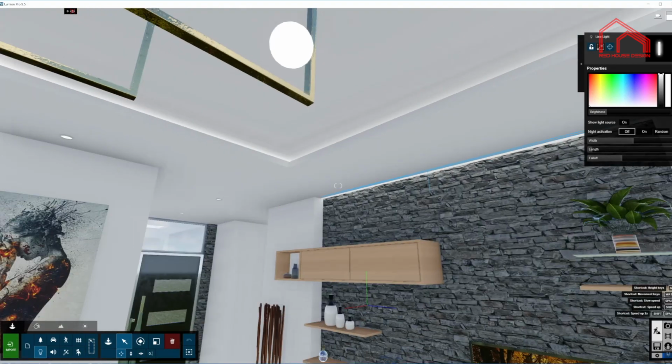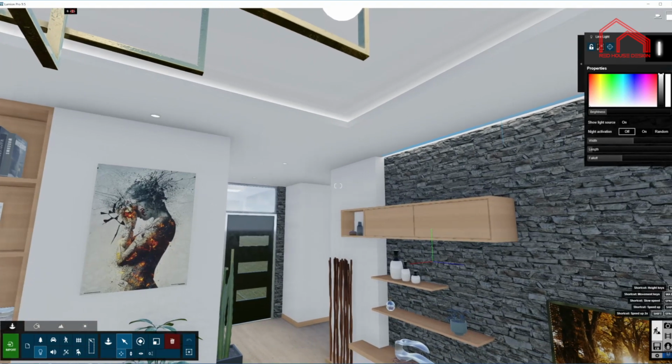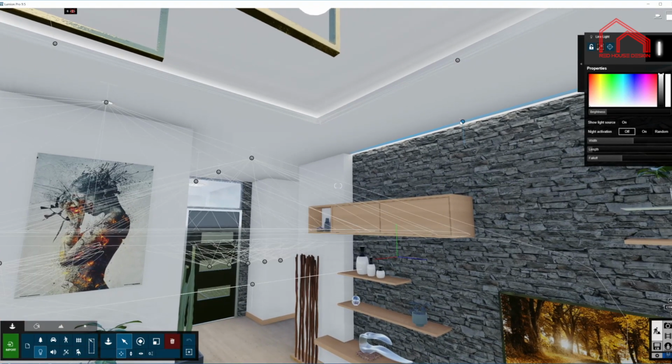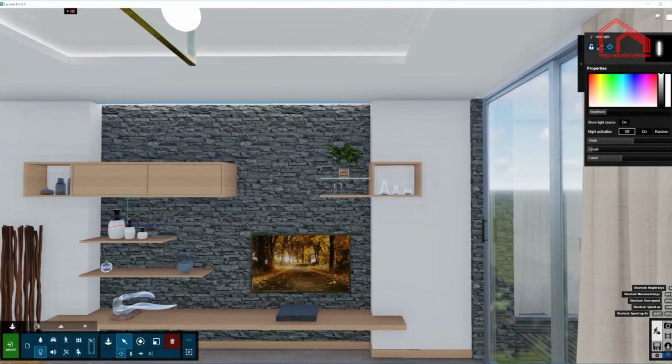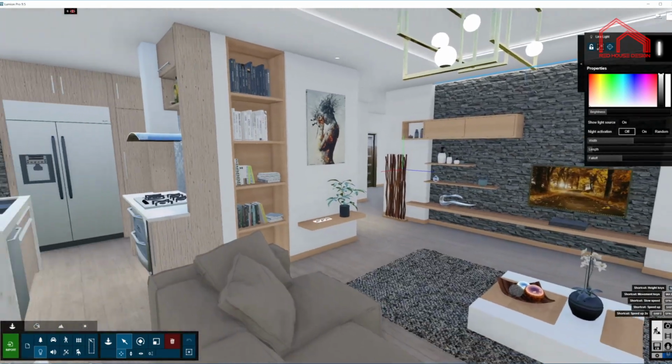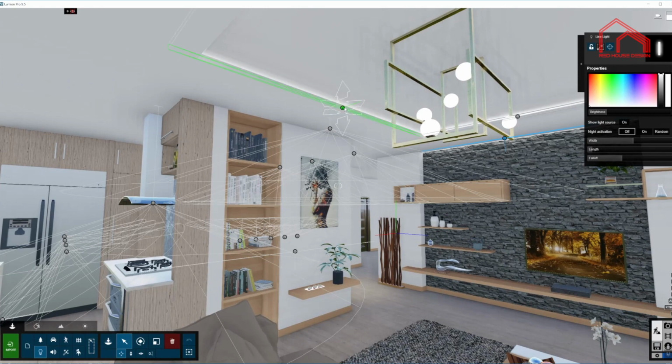As I said before, these lights, the line lights, do not cast shadows, one, and two, they go through the materials. They will penetrate the materials and they will light up the scenes that you don't want them to light up. So that is the reason you need to find a really nice balance between the brightness and the fall of the light itself.